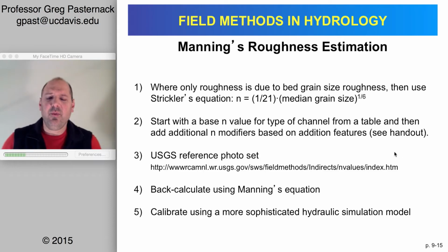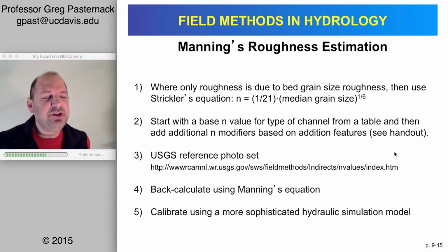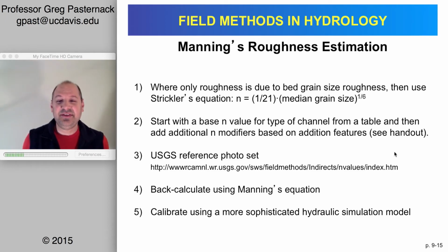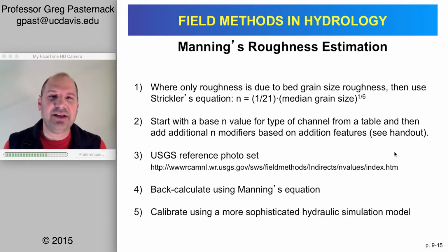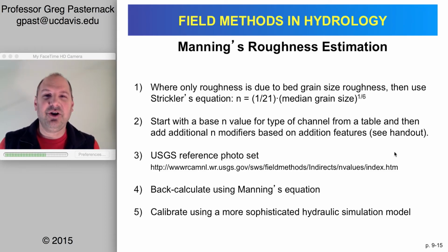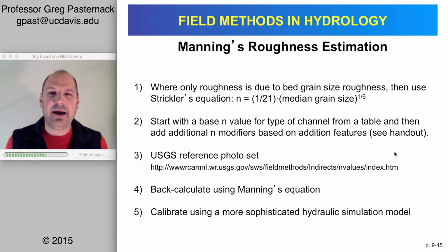So how do you figure out what value to use with n? Well, for those of you who took my HYD 143 class already, if you dig back into your brains or go back and watch a video podcast, we've seen this little beast before. We used it when you were doing your hydrological modeling, and we had to figure out how fast water was moving down the rivers, which is what we're trying to do now. And I think I gave you a value of 0.07 for grassy surfaces and 0.04 for the river. But it's a value that is somewhat expert based.